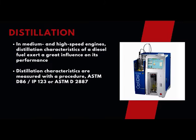For example, cloud point and cold filter plugging point are commonly used in fuel testing, while freezing point is tested in the aviation fuel industry. So, for aviation fuel, the important test is its freezing point, because the flights will be operating at an altitude of 35,000 feet. At that particular elevation, the aviation turbine fuel should not get frozen, and the pour point is a specific test for new or used lubricants or greases.